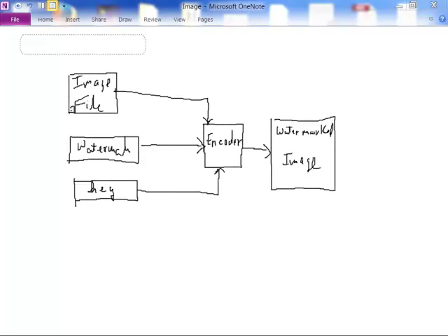One way to do this is to consider that an IP design is really satisfying a constraint problem. The constraints that we put on the problem are the design requirements. If we extend that idea, a constraint-based watermarking technique would translate the signatures that we want to embed into a set of design constraints on top of the original design constraints.